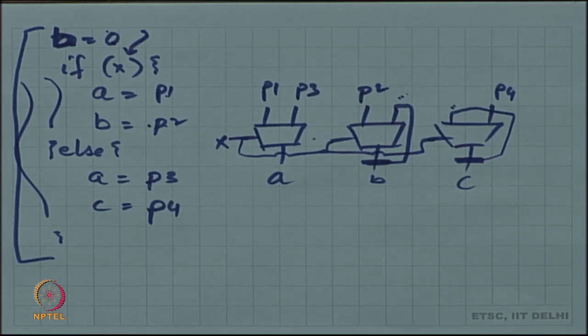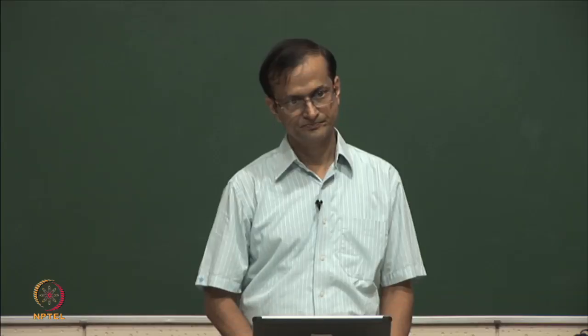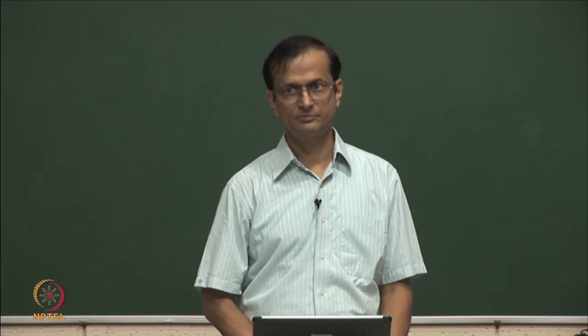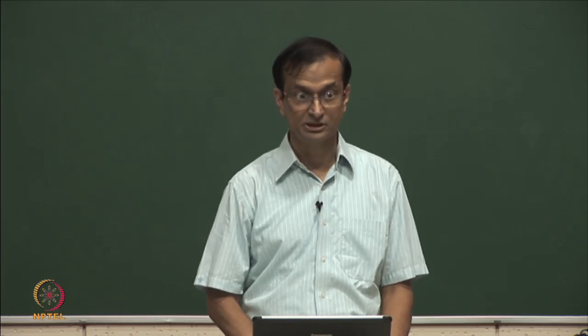Sir, if we have some single assignments in the if block and in the else block we simply say wait until clock pulse, then latches will be created. Wait until, if you have wait until at random places, then memory is inferred. There is no way around it. In fact, RTL synthesis tools will not allow you to put wait at random places.